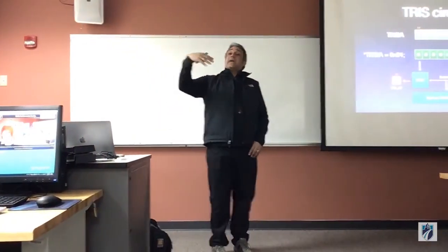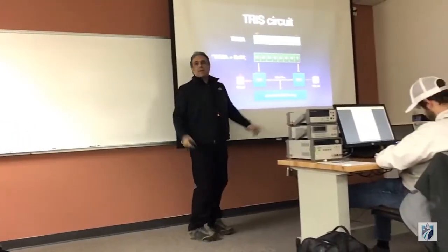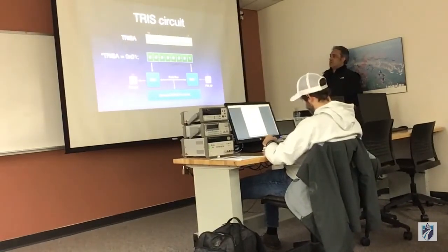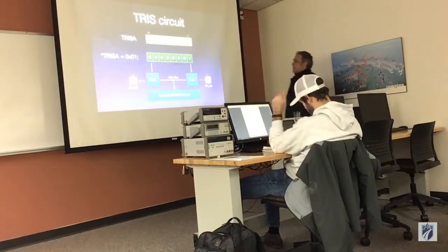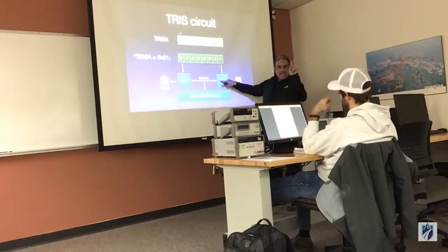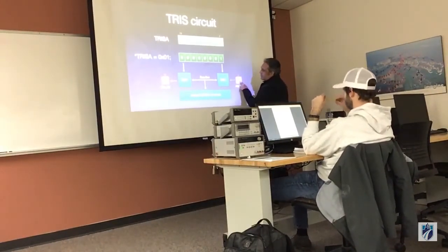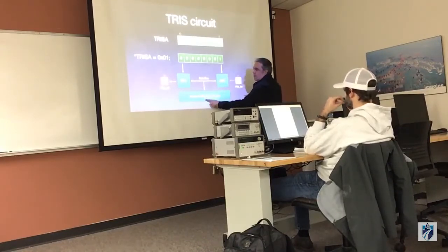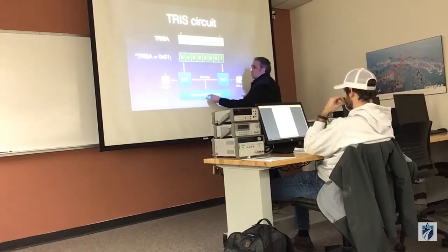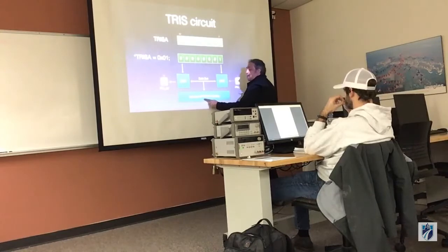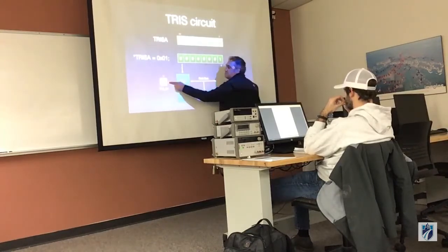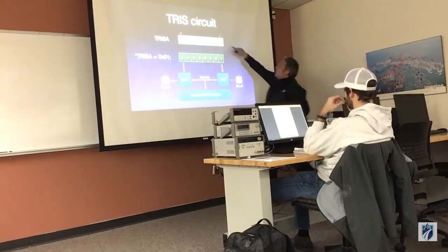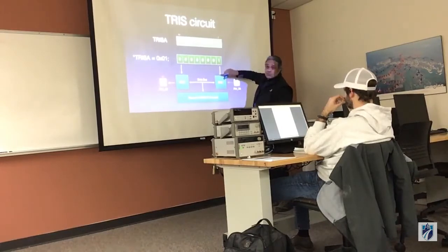So think about this data direction circuit, this DDC circuit. By the way, I'll be posting this online, so just want to make sure that you know that this is available. But here's the deal. This circuit has the ability to either draw information from the outside world to the inner circuits of your microprocessor, or you have the ability to draw data from the microprocessor through the direction into the outside world. But if you notice, that cannot happen unless the tri-state is choosing the direction.